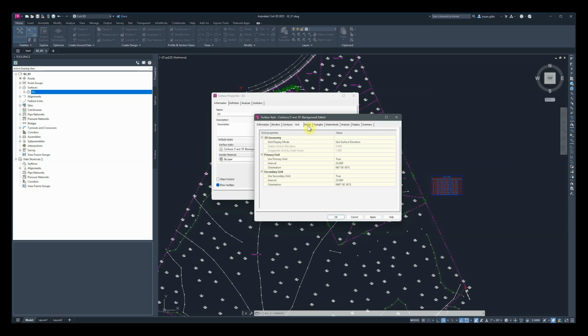And then jumping over into our Points tab, again, we have 3D geometry options. We have the ability to change styles for our point sizes and our point displays. We've already looked at a lot of methods for adjusting those on lecture 2, so we're not going to go too deep into all of that. Our triangles, so this is when we're talking about our actual tin surfaces, how these are going to be defined and styled. So again, we also see that we have the ability to change our surface elevation to flatten or exaggerate elevations, which open up certain editable attributes then.